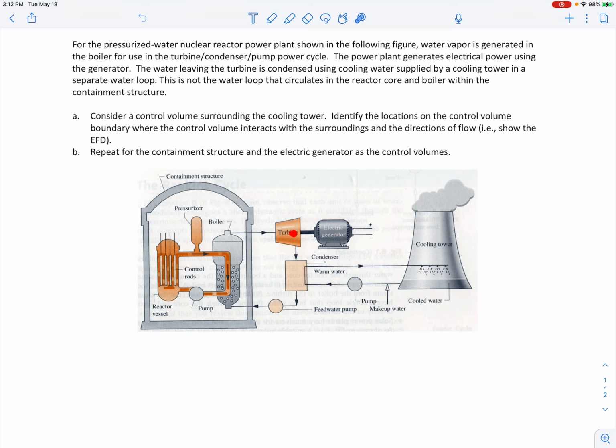So the steam goes through the turbine, and then it goes through a thing called a condenser. You'll see this later in the course, but you remove some residual heat from that steam. In this condenser, it could still be mostly steam coming in, and it'll cool down and turn back into water, and then you'll have water coming out here. This is a feed water pump that just circulates the water back. Water again here, and then it heats up and turns to steam, and then it just repeats that loop.